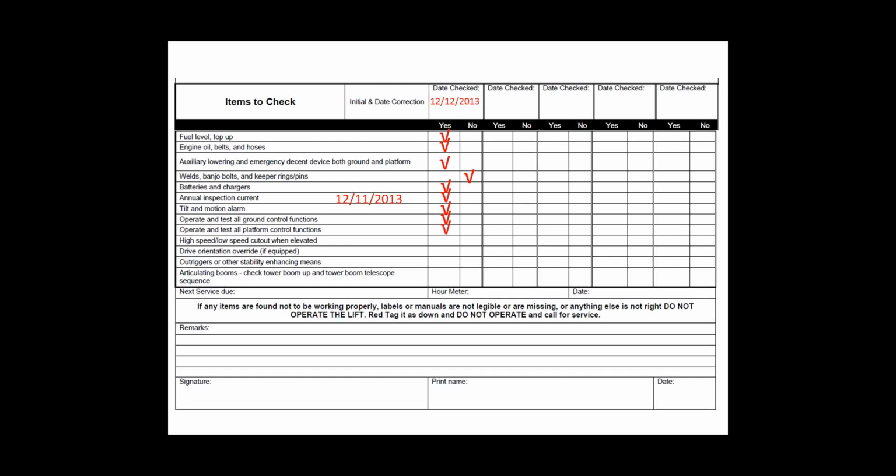In addition, we have high-low elevate cutback speeds. Some machines only have one safety switch. Some machines have 2, 3, and 4, depending on the make and model. So if we have 3 elevate drive cutback switches, we need to test all 3 elevate drive cutback switches.